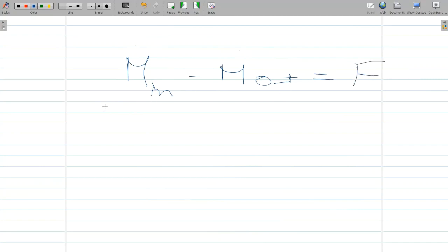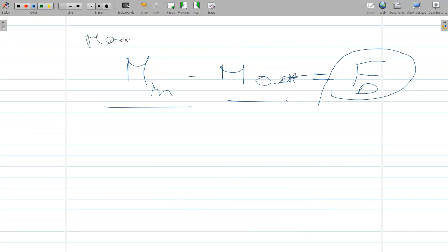So the flow will come in with a higher momentum and leave with a lower momentum, and that momentum is being consumed by the drag force exerted by your airfoil, right? So this analysis can give you the net drag force that is acting over your airfoil. So momentum of the flow coming in minus momentum of the flow going out will be nothing but the net drag force acting on your airfoil. This is the momentum conservation law.